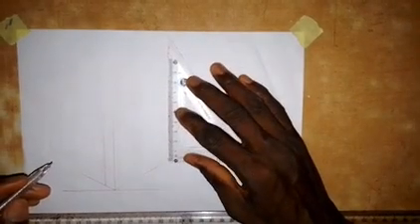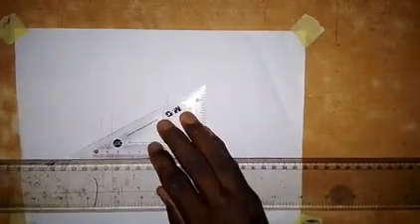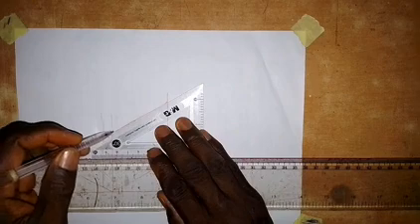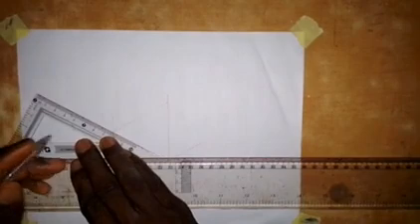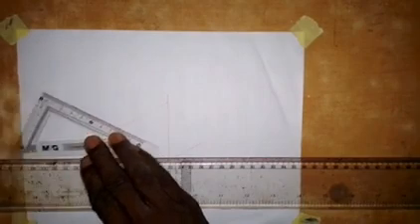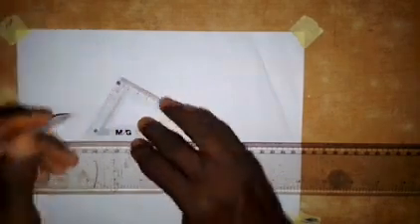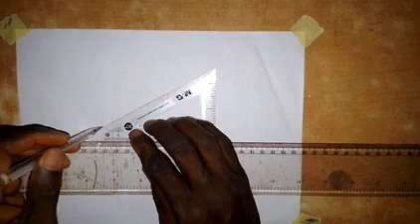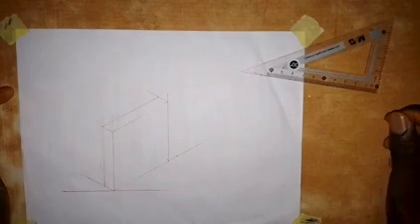So we take it here from 0, and this is 60 millimeters here. So we are going to draw a line from this point to touch this line, and then we turn our set square like this and draw a line in this direction. I will come here also, coming to this point here, I will draw a line in this direction, and then I will turn the set square like this and draw a line to touch this line. Alright, so this is what we have to do first.